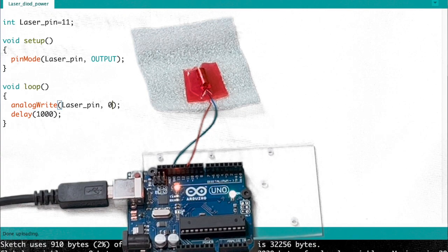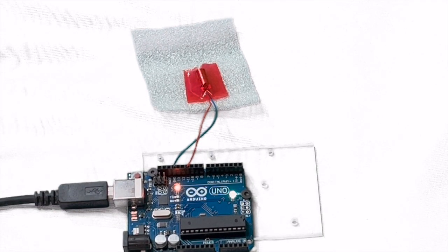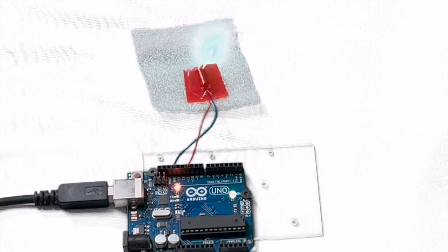And this is basically what you have: a 0% duty cycle, and your digital signal is basically 0. So this is how you use the pulse width modulation provided by the Arduino board to control various digital circuits. It all works very nicely to control the LED or the laser diode brightness, but we seem to be using two complex devices, such as the Arduino, and then a laptop to control them.